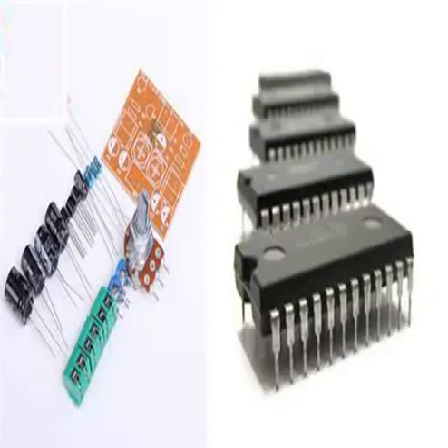The main disadvantage of ICs is the high cost to design them and fabricate the required photomasks. This high initial cost means ICs are only commercially viable when high production volumes are anticipated. An integrated circuit is defined as a circuit in which all or some of the circuit elements are inseparably associated and electrically interconnected so that it is considered to be indivisible for the purposes of construction and commerce.